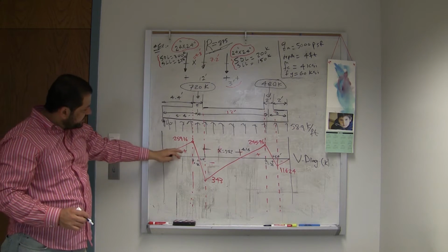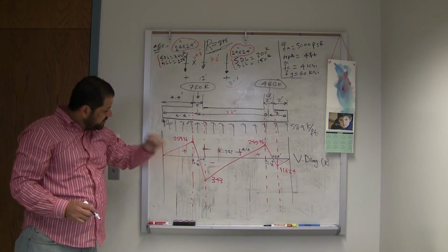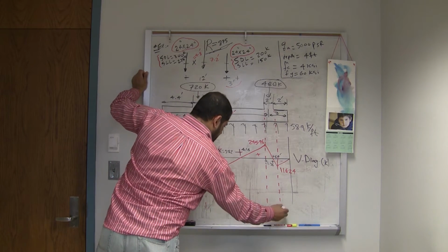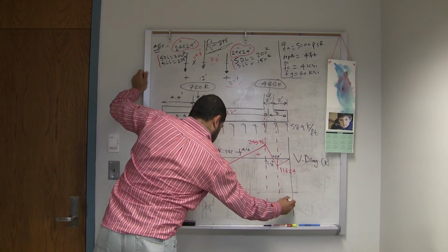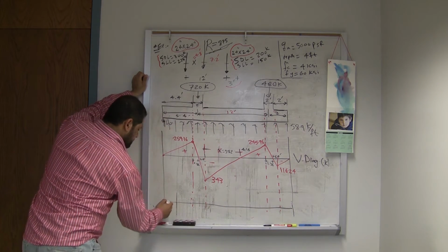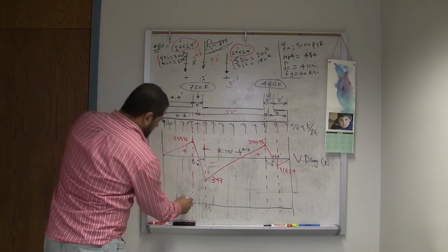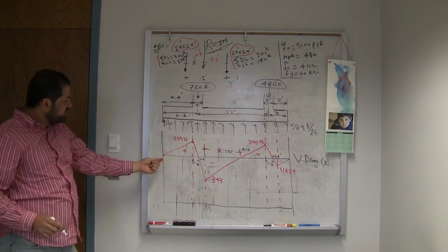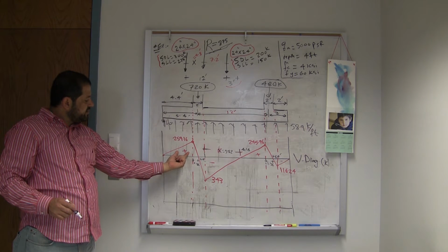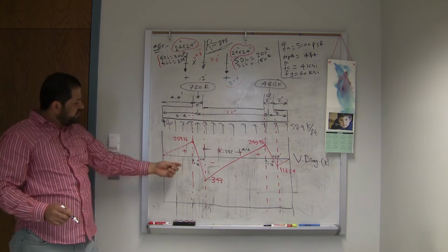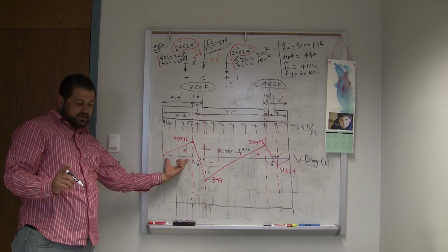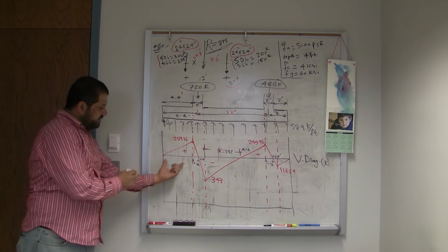We will be positive here, then we're going to be negative. So this is going to be our moment diagram. To the face, this area here is 4.4. Look how you do it, Gerard. It's a triangle. This is 4.4, times 259.16.